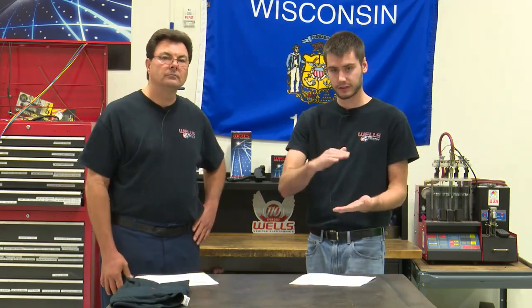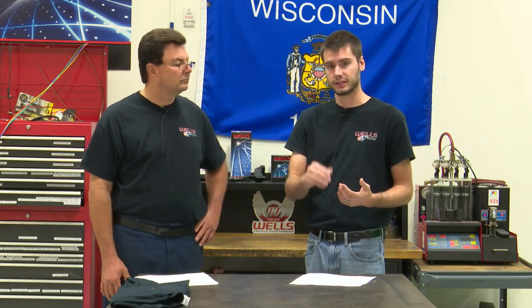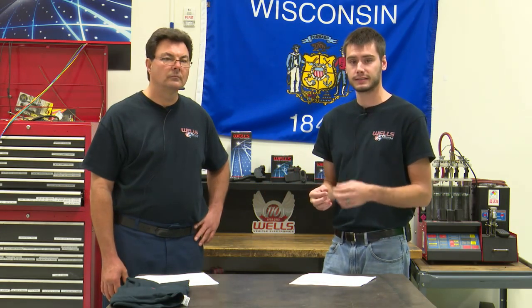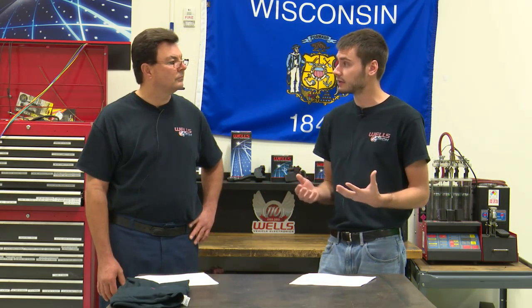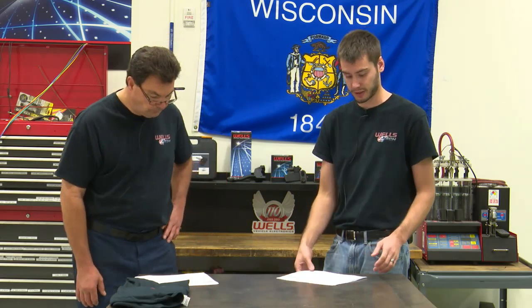So the computer has essentially got a checklist. It checks off that all these conditions are met, then says okay, I'm good to run the test. It runs that test for 10 seconds and either passes or fails. If it fails, it sets the DTC as maybe a pending code, but it doesn't immediately illuminate the check engine light. Right, it has to fail twice.